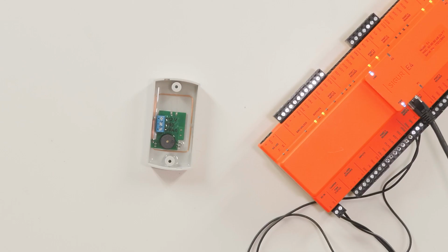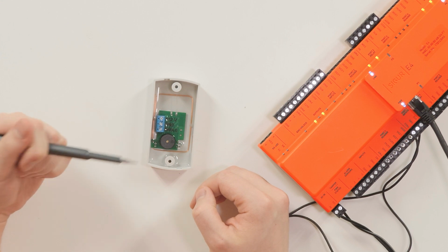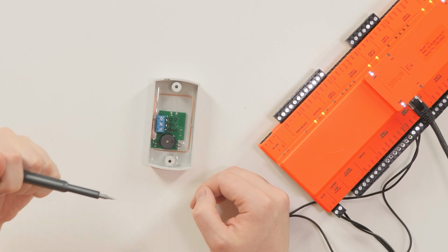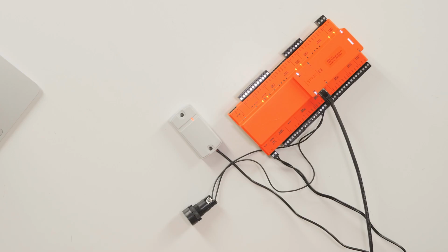In our example, this is Matrix 2. This reader does not have built-in lines to control its indication. Only power connection lines are available, 12 volts and GND, and data transmission, Data 0. To demonstrate the reader's operation, connect only the device's power line and present an authorized card. The reader was able to successfully read the identifier and accurately played the light and sound indication. Now let's present an unauthorized card. We observe the same indication, as the reader does not have the capability to control its indication with external devices.